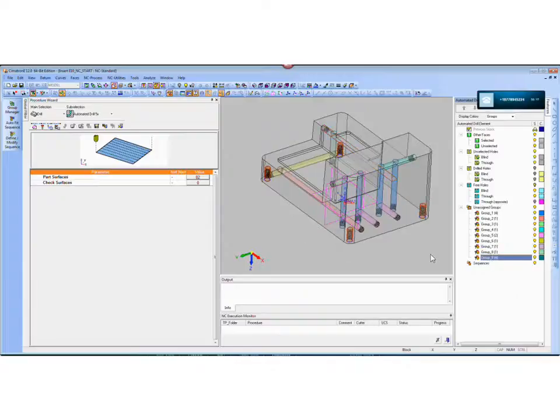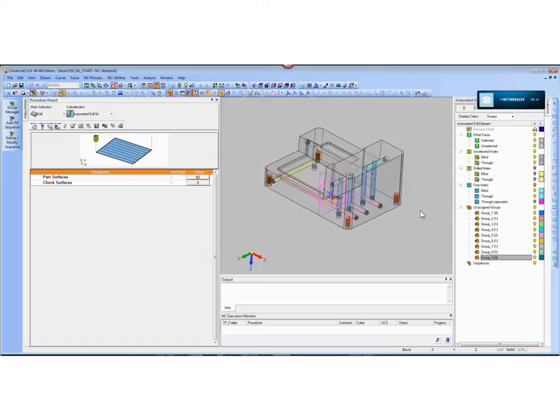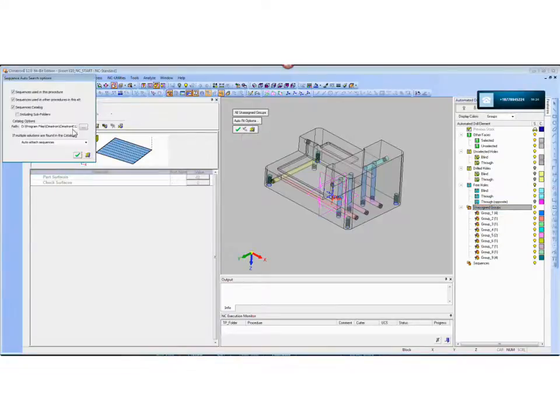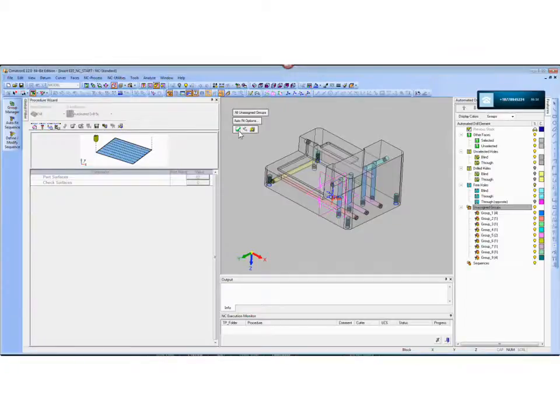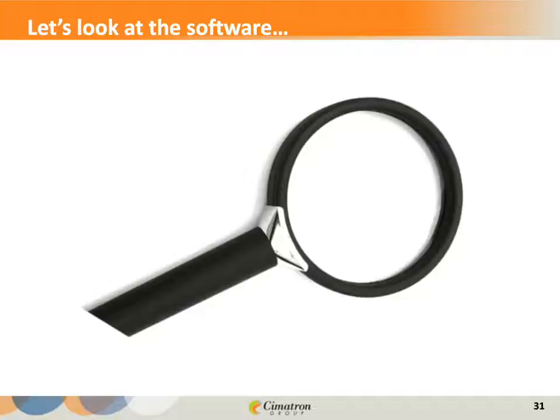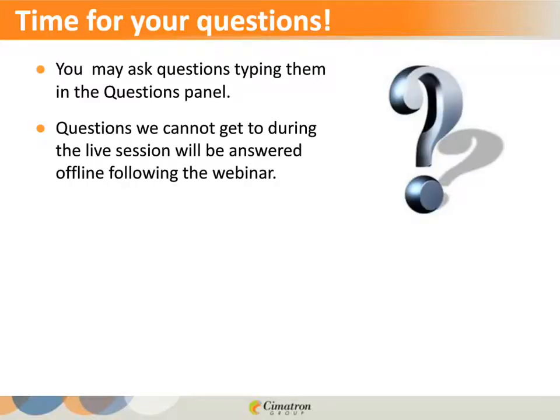So now we're going to process them, and I'm going to choose auto fit sequence. Let me just verify that it's looking in the right folder and choose OK. It says for 9 groups, an appropriate sequence was found and attached. And we're going to save and calculate. This is where we're going to start to talk about the difference between automatic versus automated.